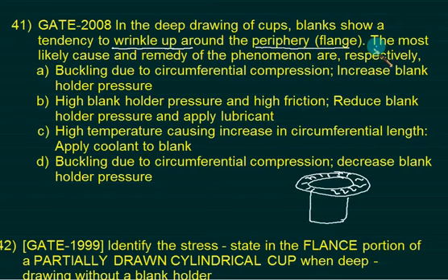But what he wants to say is the most likely cause and the remedy. Cause is what? Buckling due to circumferential compression. What is the remedy for this? Increase the blank pressure. First is the cause and second is the solution for it.